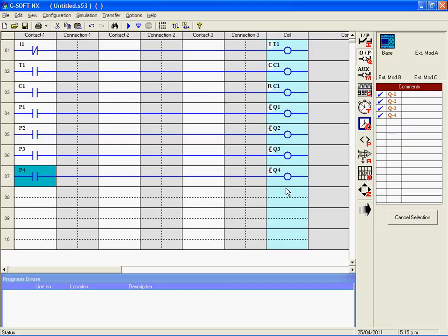Now I've used a timer there as an input, but you could equally just use a standard input which could be coming from a magic eye, a proximity sensor, a bottle counter, or something similar. And you can use all sorts of logic in there to control things. I'm just showing a very simple application of counting and comparing to create an output cycling lamp or something similar. Okay, simple as that.